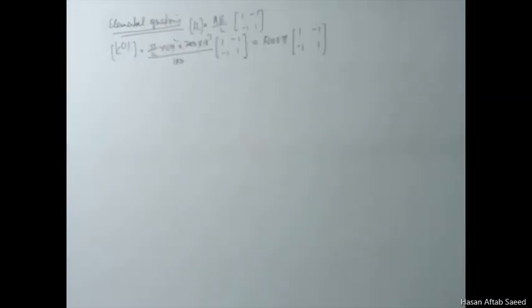As you'll see in this problem and in all penalty method problems, we use a very high penalty number C, and because that is very high and it gets applied to many diagonal elements and some off diagonal elements also, as you'll see, the system becomes very sensitive to any errors. So we would like to use accuracy as much as possible.